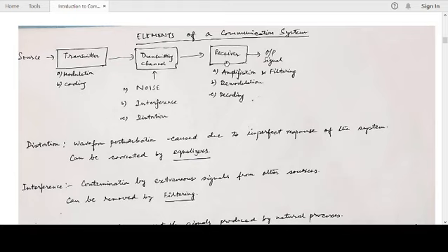In the receiver, first the signal received is very weak in strength, so appropriate amplification and filtering of the signal is performed to reduce noise and interference. Then just the inverse processing is done as in the transmitter. For example, instead of modulation, we do demodulation. Coding is done in the transmitter; the coded signal is decoded in the receiver, and finally we have the output signal.